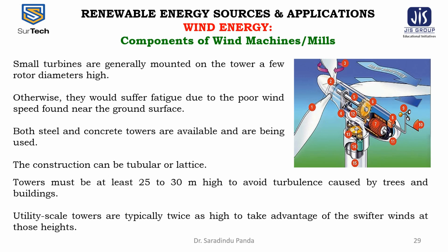The resonance frequencies of the structure are determined by complete modal analysis, leading to the eigenvectors and eigenvalues of complex matrix equations representing the motion of the structural elements. The wind fluctuation frequencies are found from measurements at the site under consideration. Experience on a similar nearby site can bridge the gap in the required information.